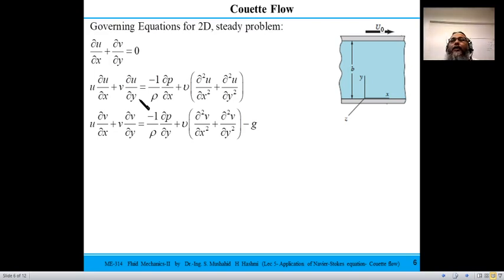Secondly, which is not mentioned here, if you see, the gravitational force in x is not there, but the gravitational force in y is there. So we have 2 momentum equations, one in x, one in y. Why we don't have it in z? Because it's a 2D problem. Similarly, in the continuity equation we have a simpler version. Once you write down initially that it's a 2D problem, you can write the 2D governing equations. So you have the complete Navier Stokes equation in 2D.